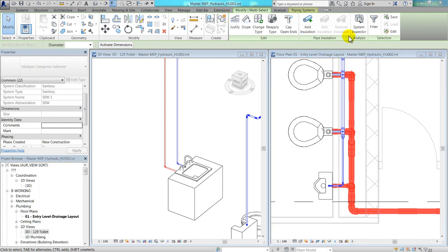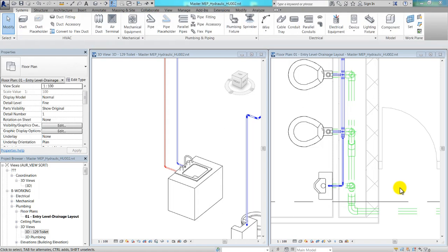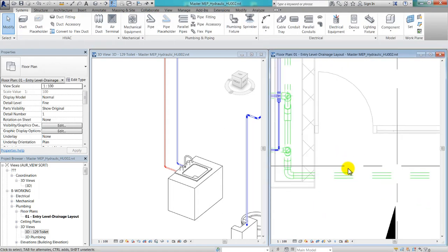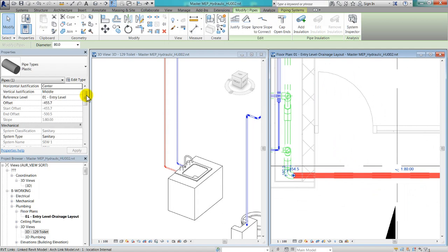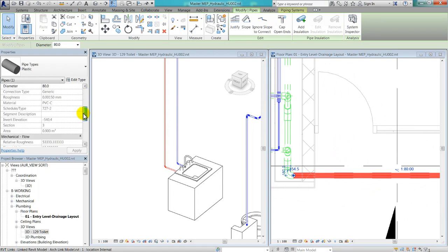Flow calculations and therefore sizing of pipes that are not under pressure or not fully filled with a medium, as sanitary pipes usually are, are much more complex. For sanitary, the usual workflow is to use the model to calculate the fixture unit totals and size them accordingly. Schedules are very powerful to verify this process. Refer to module HU003 Advanced Scheduling Hydraulic.